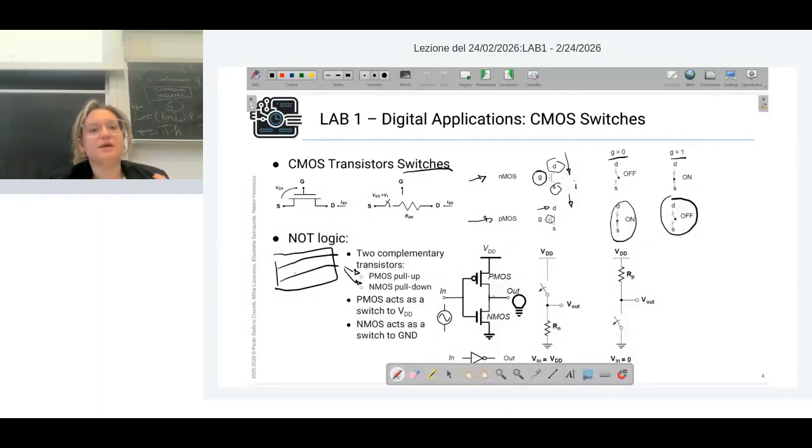As you can see here, we have two transistors, a PMOS and NMOS. Why two if I can use just one, right? Because I told you that one in both ways can be on and off. So why do I use two of them? Because with the two of them, you have more control on the power distribution, of the power consumption, and so on of the circuit.